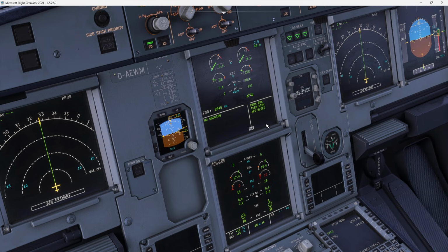And we keep monitoring that the engine does not pass here EGT, the values, and the N2 is going to stabilize at 59, more or less, and this one at 30. So we keep monitoring this. Available, so N1 stabilized at 18, N2 at 59 as I said, and EGT below 450, 725, and the pressure is at 34, 35. We had a good start.